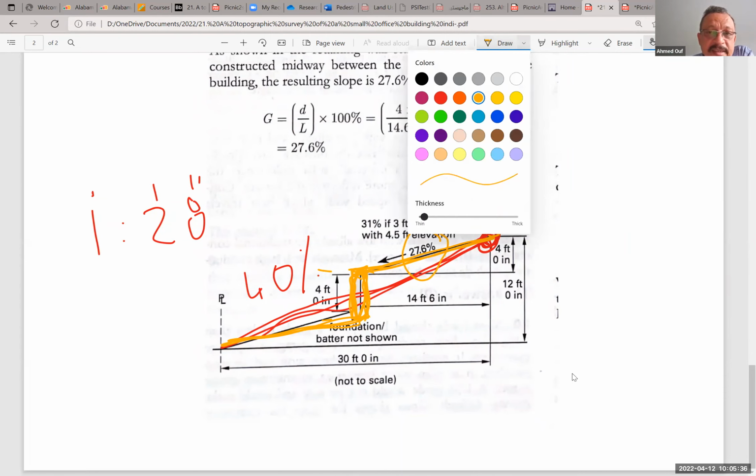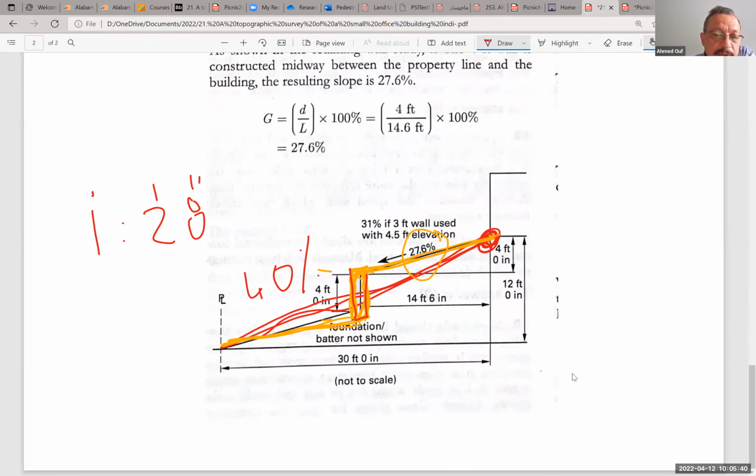But what it entails is building a wall here. This wall is not cheap. I mean, this is an additional cost to your project. So when you do that, you can still mow the grass. You can work with a larger slope, but you are creating a wall.